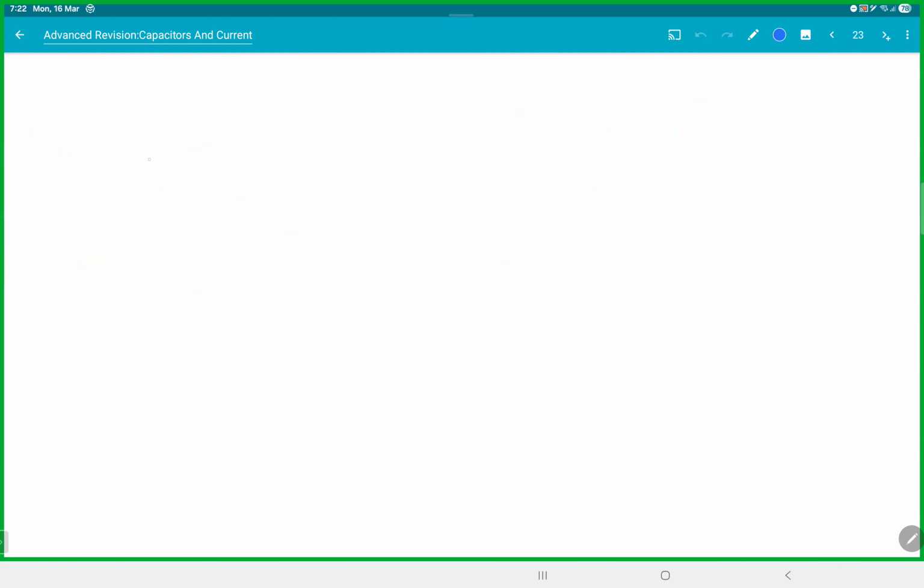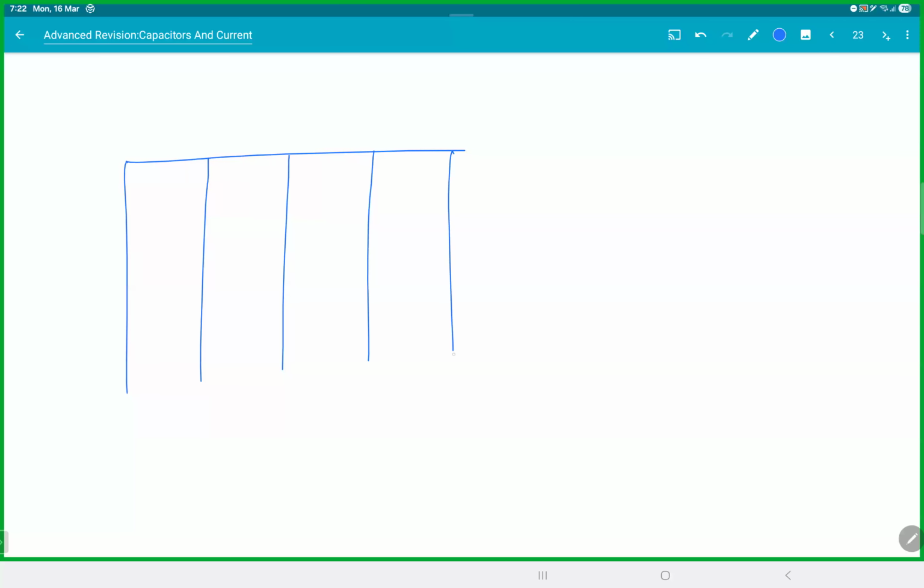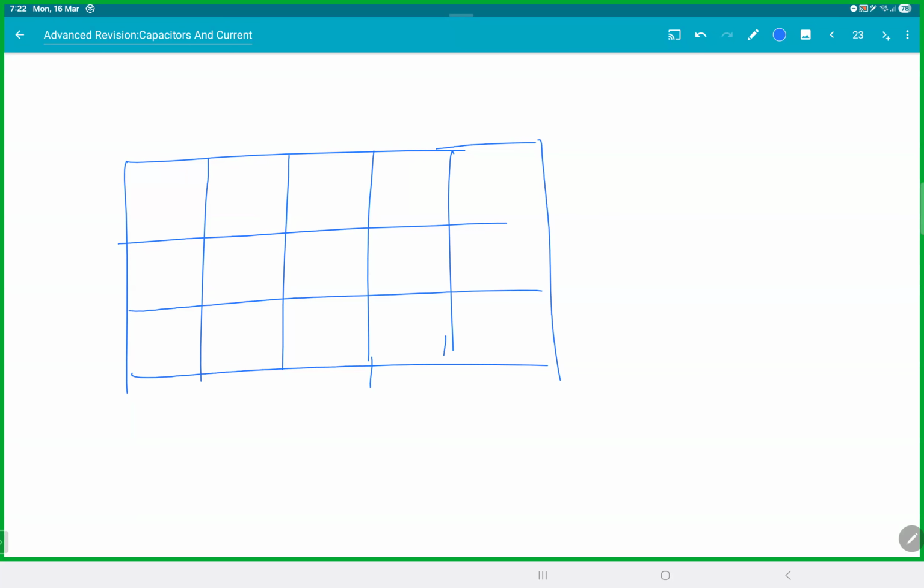Now, if I do both at the same time, when I give current I here, this branch is I by 2. And remember, this branch used to be I by 4. When I pull current I from here, this is also pulling I by 2. And this branch is pulling I by 4. Make sense?